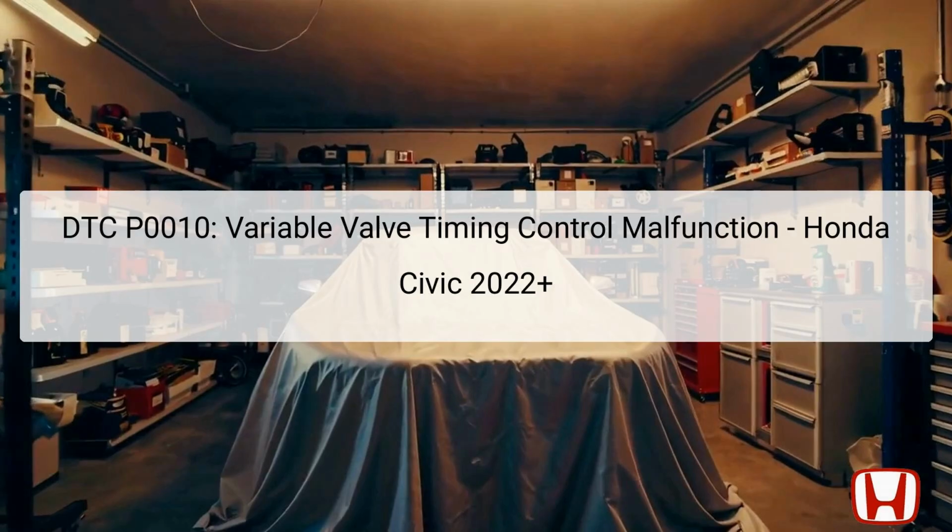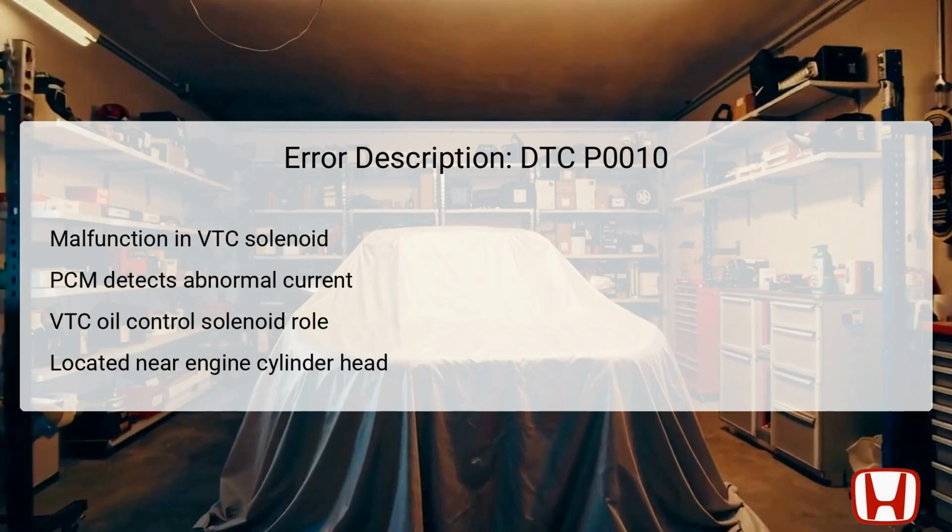load conditions. DTC P0010 indicates a malfunction in the variable valve timing control oil control solenoid valve A. The solenoid's primary role is to manage the flow of oil to the VTC system, impacting how the camshaft timing is adjusted. When the PCM detects that the commanded current differs from the actual current flowing through the solenoid, it identifies this as an abnormality. This abnormality can hinder the solenoid's proper function, leading to unsatisfactory engine performance.